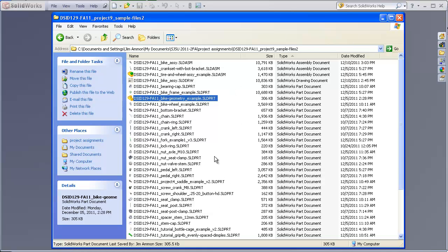One way to do this perhaps is right after you do your pack and go to put your entire project into one folder. Then you can go and start renaming things without worrying that there's a file somewhere that is unaware of a name change. One other thing that people don't realize is that a drawing that has views of any parts or assemblies will not be able to show those views if a name change has been made also, because the drawing also can only know where to find the files based on their name.